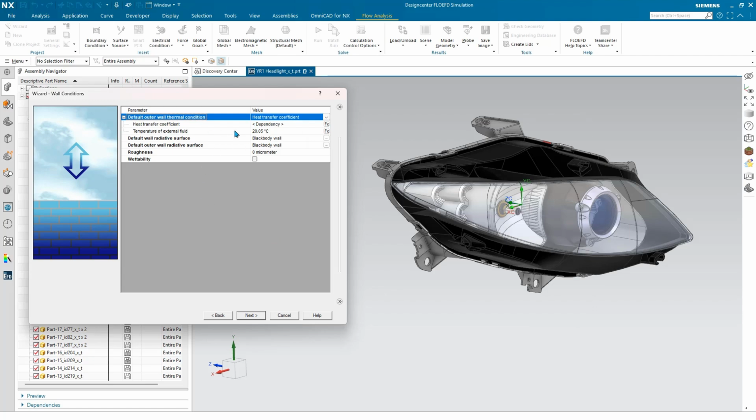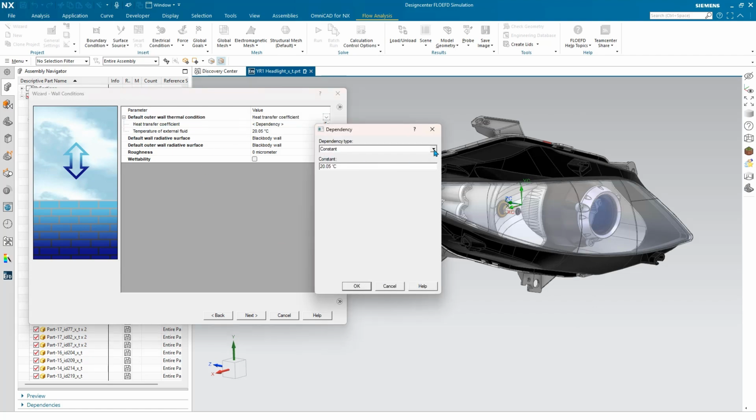Similarly, we'll be doing this for external fluid as well. So now the condition that I'm trying to simulate here is that my car was turned off at the very beginning. So when it started, the temperature was slightly higher, and this temperature was coming from the engine bay, which is 40 degrees Celsius. At 1200, it was still 40. Then again at 1200, now I'm going to choose this as negative 20.